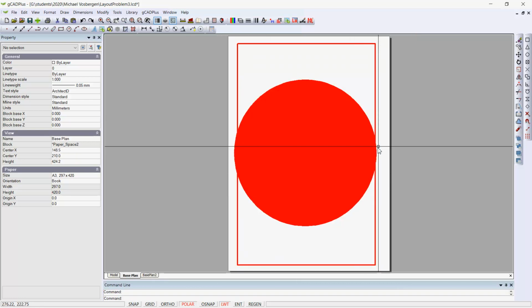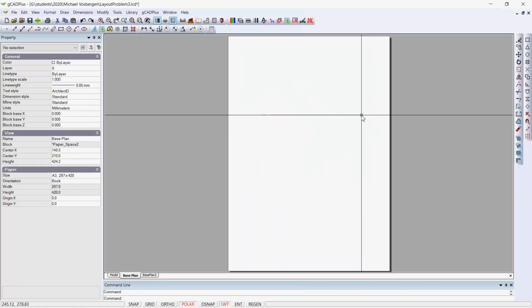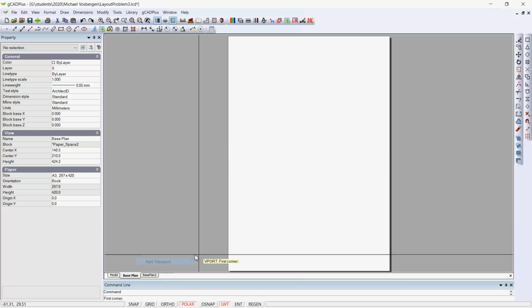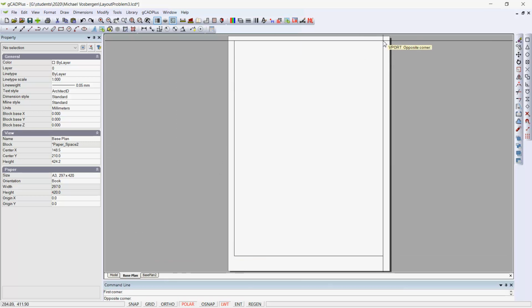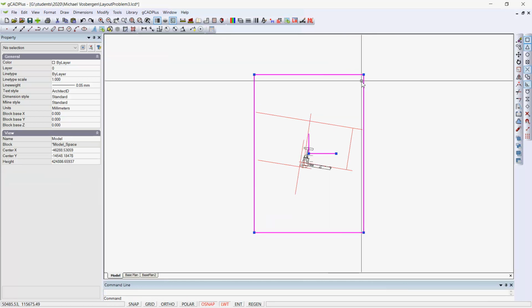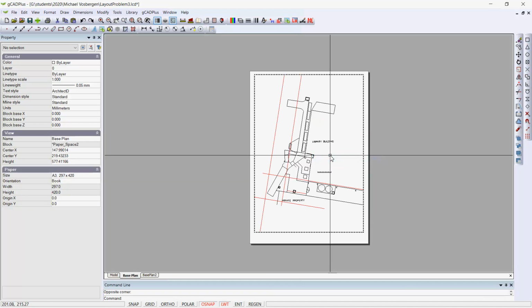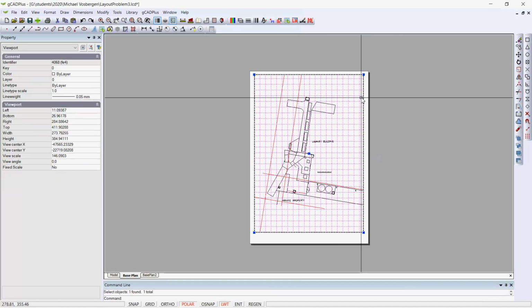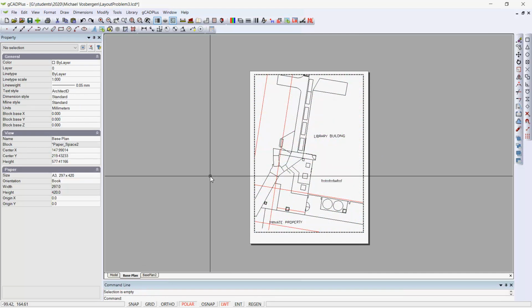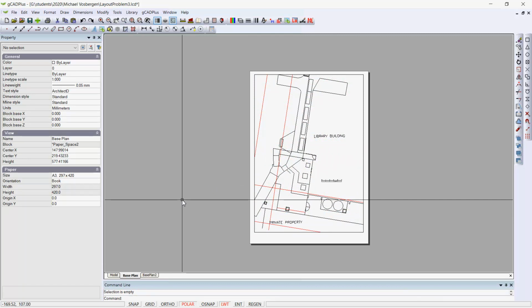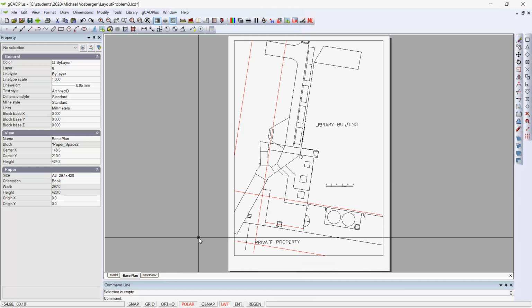There, that's what I did with the drawing sheet, to be able to try and see it as I zoomed out. So I'll do that, and now let me add a viewport, pop it in here. There's a viewport. We can double click in there, set it up pretty much as though it was done before, like so. Display it on the layout. We'll pick the floating viewport, give it a scale of 100 and make it a fixed scale, and get out from there. Now what I'm hoping to see is that I can just zoom extents. So zoom extents, and it works perfectly.